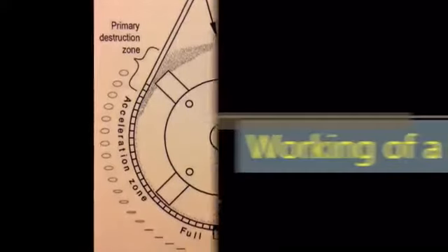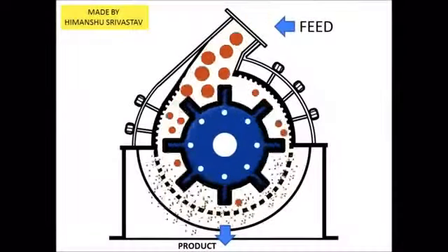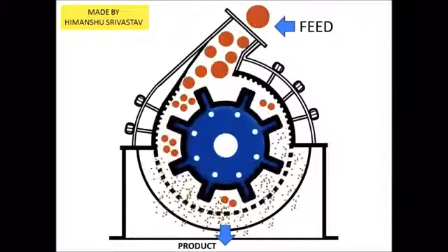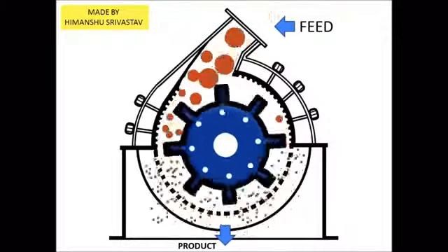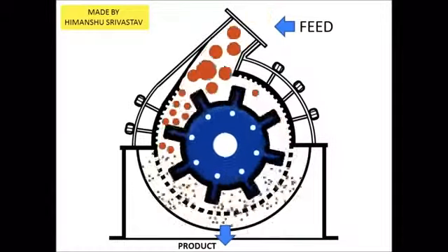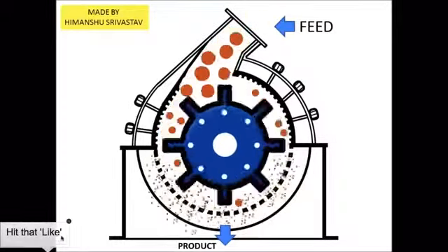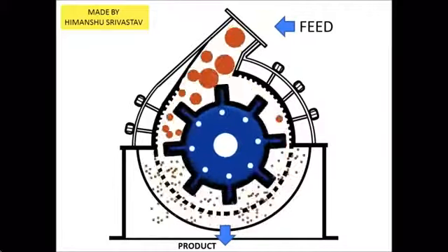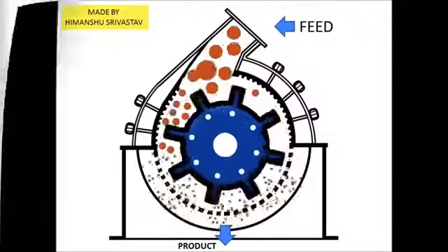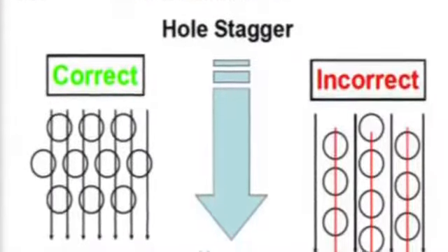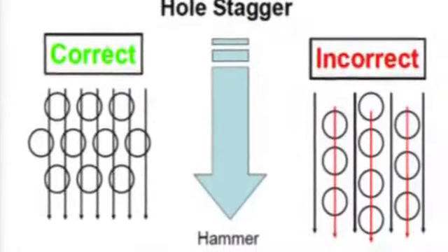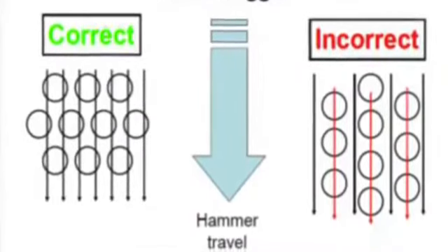shear and compression. How impact grinding occurs in a hammer mill is that a large, full-size kernel or ingredient falls into grinding chambers where hammers attached to a shaft are moving at a very high velocity. These hammers make contact with the ingredient, breaking it into smaller particles. The particles then either fit through the screen or bounce off the screen back into the grinding chamber, where they are hit again until they are small enough to fit through the screen.